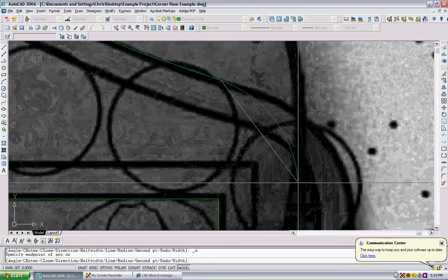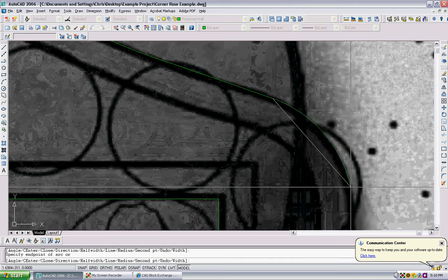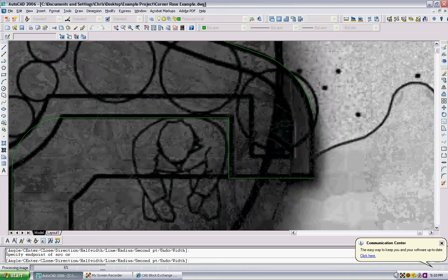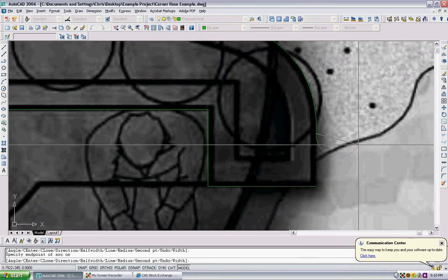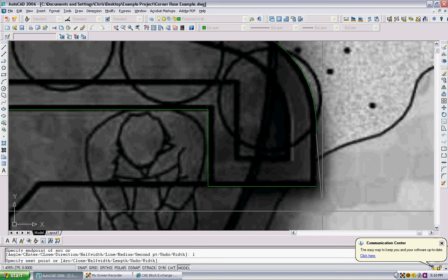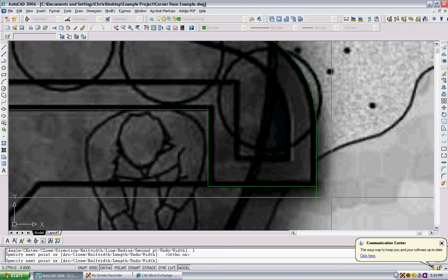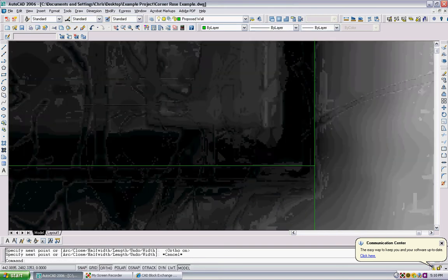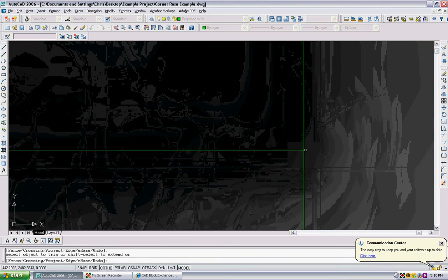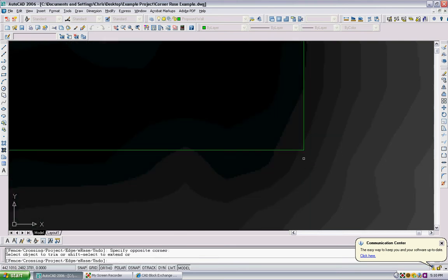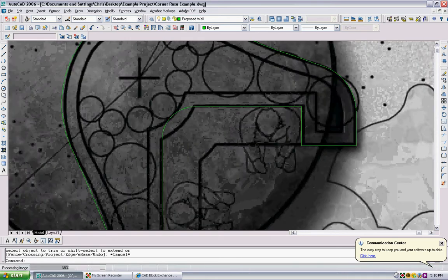You can always Control Z on the line too to go back where you want it to. Here and there, and I'm gonna hit L again and put my ortho back on and come straight down. There we go. Hopefully, yeah, it's overlapping, so we're just gonna trim that. Okay, and then we should have our shape minus that little lip right there.